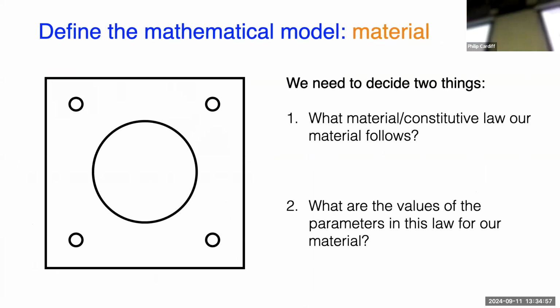So governing equations, geometry, material behavior. Of course, steel or aluminium or whatever this plate is, under certain loading conditions, you might get plastic deformation, permanent deformation. And under certain temperatures, you might get visco behavior. And depending if it's rolled, it might be anisotropic. It might be inhomogeneous, you'll have certain grain structures. That probably doesn't matter for this initial stress analysis.